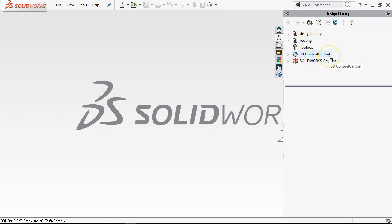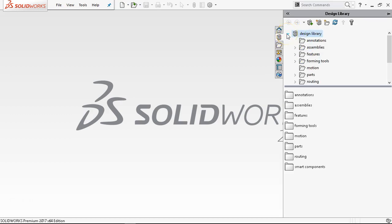We talked a little bit about the toolbox. Toolbox is inactive because I am not in an assembly and I have not turned it on. So those are my two conditions to do the fasteners and the hardware: I have to be in an assembly and then I have to activate that module. On the other side, the design library is available, and I can create parts and put in the library that I'm using over and over and need to have access to.